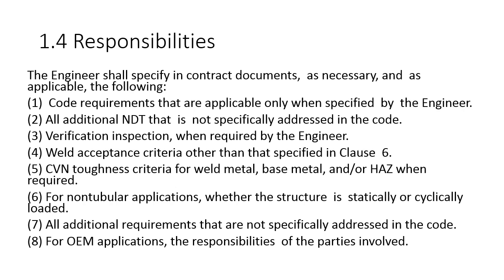Code requirements. Number 2 is a big one because if the engineer wants additional non-destructive testing, that they looked at their joint configurations and they see that they need more non-destructive testing, they'll throw it into the contract documents. Okay, we want this much. We think that this is an ultra-critical weld. We need it ultrasounded, dye penetrant, mag particle, everything. We want all the NDT processes done on this specific set of joints. They would address that in the code or in the contract documents, excuse me.